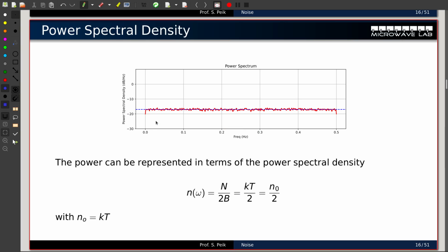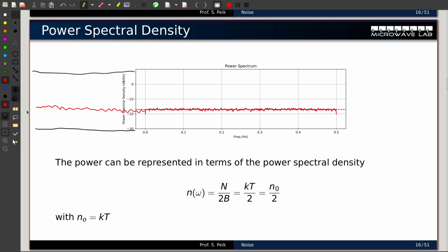Now, there's a little twist to it that comes from the fact that system people like to also look at the negative frequencies as well. When you look at negative frequencies as well, then your signal keeps going like this here. And now your bandwidth in that area is not 0.1, 0.2 in positive, but also 0.1, 0.2 in negative domain.